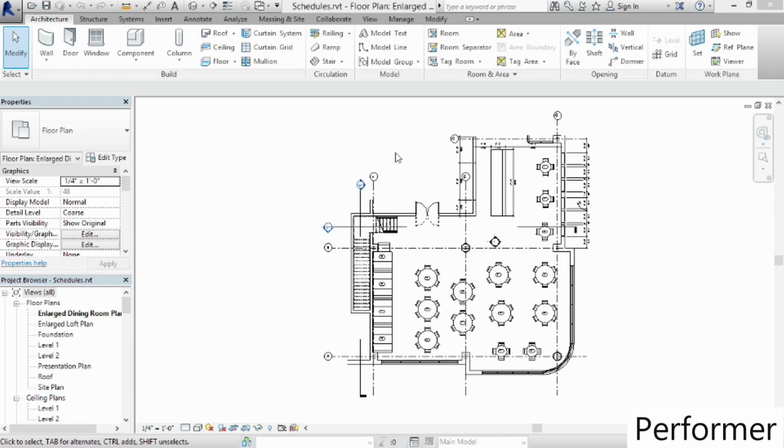In Revit, a schedule is a live view of the model. So you just simply ask Revit to go look through your model for a certain category of information, and it will list out all those items for you in a table automatically. Furthermore, the information is a direct live link back to the model. So if you make any change in the schedule, the model updates and vice versa. If you change the model, the schedule updates. It's a live view.